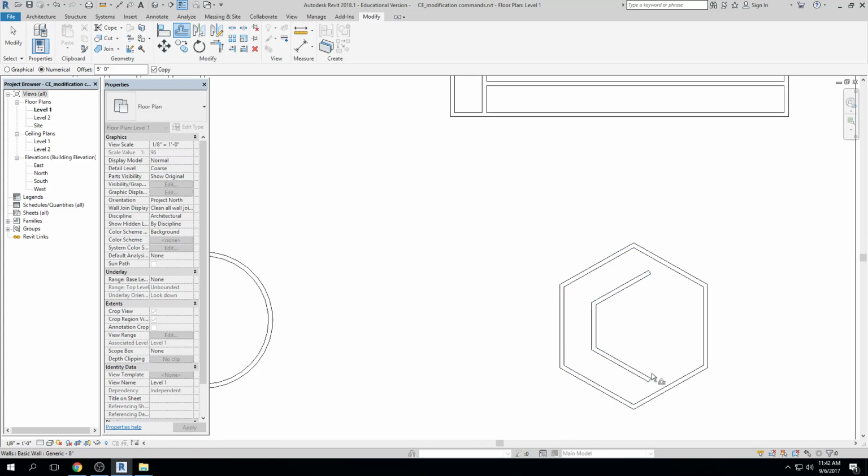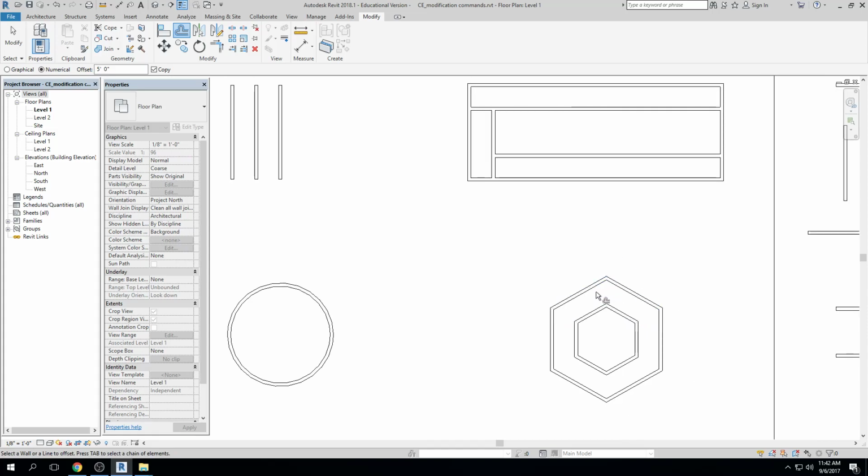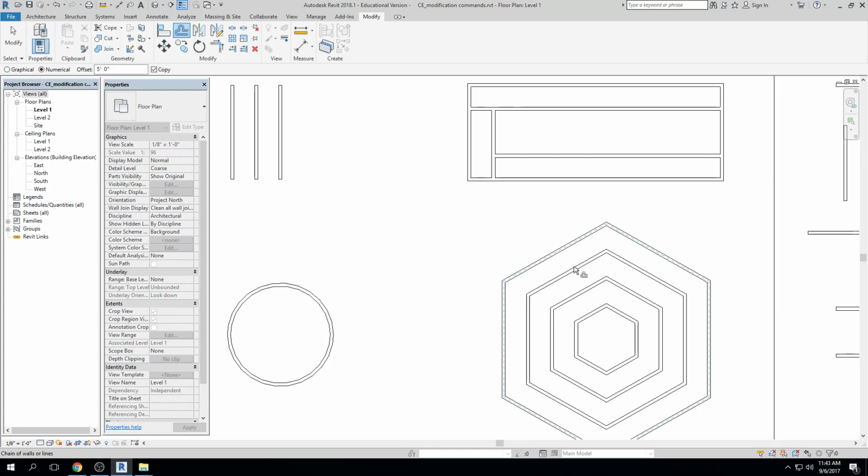Click, click, click. Right, and you're noticing that it is sort of breaking these objects up into pieces, right? So even with a hexagon, when I click on these objects, it separates them out. It doesn't uniformly pick the entire object, okay? But that doesn't make sense as the only way of doing this, right? And I want to remind you of some of our selection methods, okay? If I hover over an object, it turns blue. I haven't clicked yet. But if I'm hovering over an object and I press tab and let go, see how it selects them all at the same time? Okay, nice, right? If you hold tab, let me show you what will happen if you hold tab. You got that action going on, right? But if I just click it once, it highlights, and then I click my mouse and